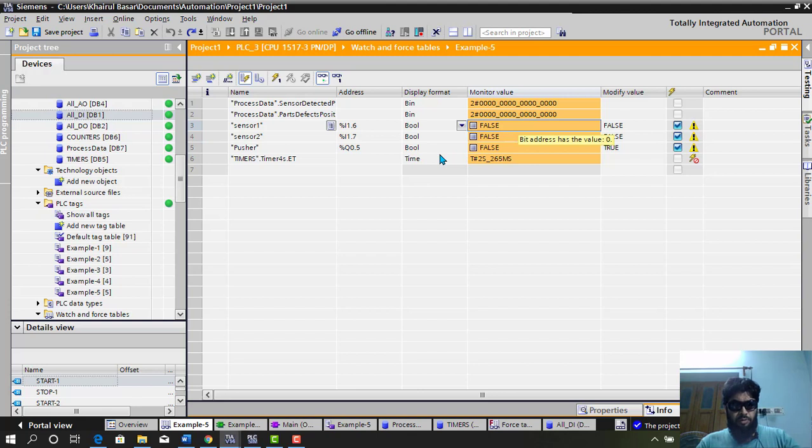If we enable sensor 1, which is entering parts into the conveyor, it will register this bit. So 1 bit is registered, 2 bits are registered, and now when one of the positions is at the 5th position, if we enable this, when it reaches the 5th position, okay, you see this defect parts 5th and 6th position is registered as faulty because it's always on.